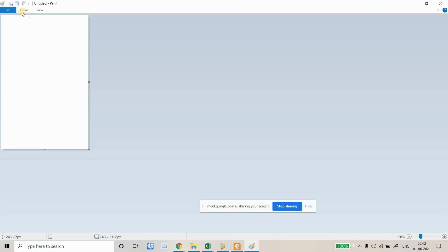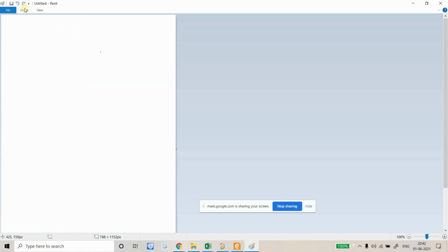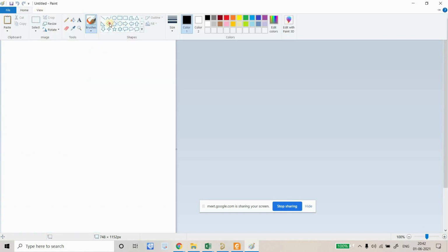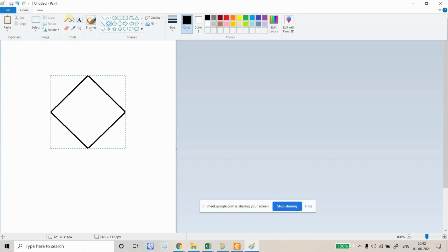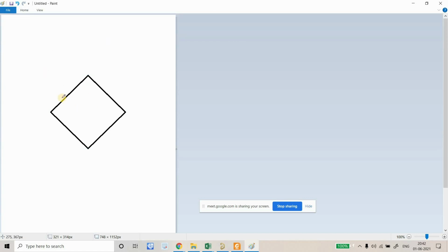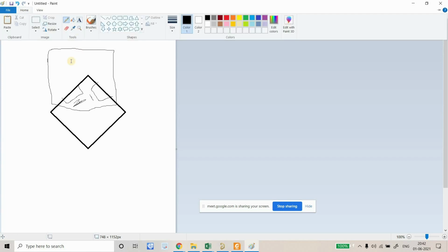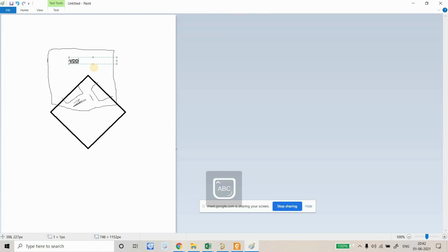Let's suppose this is our RK3399, and this is the position. Let's take it. So these are all the VDD DDR or VCC DDR. It's somewhere here, so that means one section of the plane, which will be something like this. I'm talking about power plane sectioning. So this one section of the plane will be assigned to VCC DDR. I'm just going to write it here. All right, let's see another one.